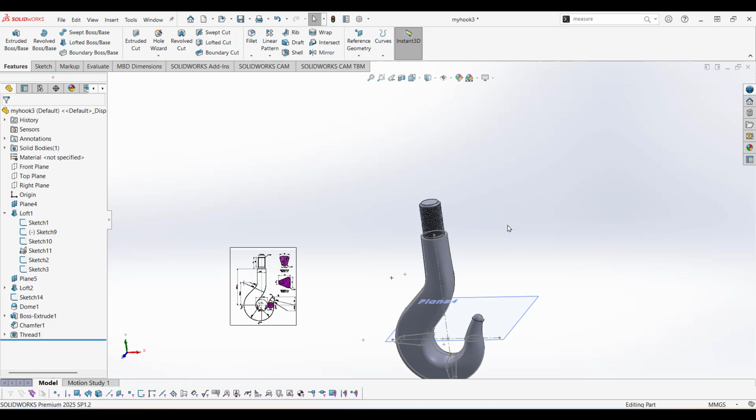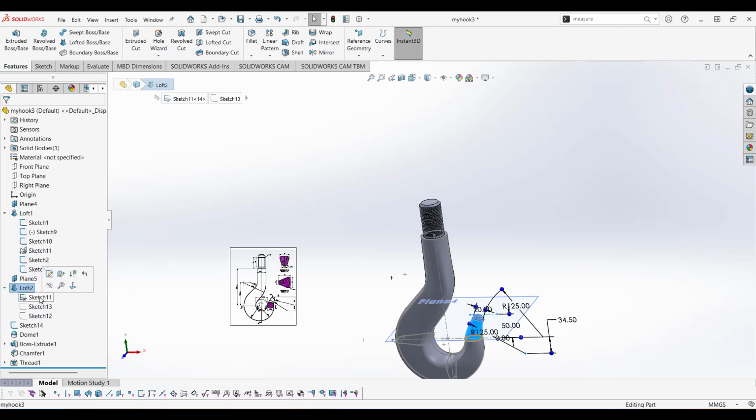And yeah, that was a demonstration for lofting. So we started by making one circular sketch here, one rectangular here, third rectangular, and fourth circular, and then this was lofted through guide curve left side, guide curve right side, and then next was a second loft which composed of a circular starting sketch, a circular ending sketch, and a guiding line.